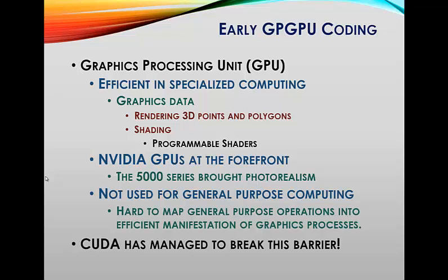The GPU typically processes a set of complex vertices that create a bunch of polygons and then maps them onto your fragmented screen, which is basically the pixels that you will see on your monitors. After that, it applies a texture, calculates and interpolates the red, green, and blue color values that are going to be applied to each pixel, and then rasterizes, or shows, the picture on your screen.